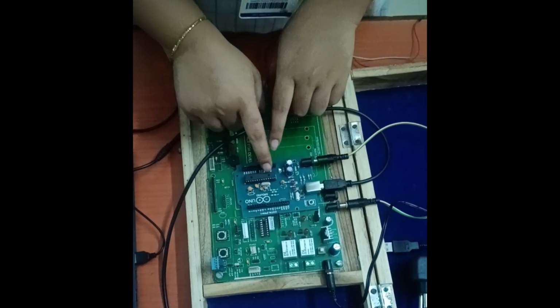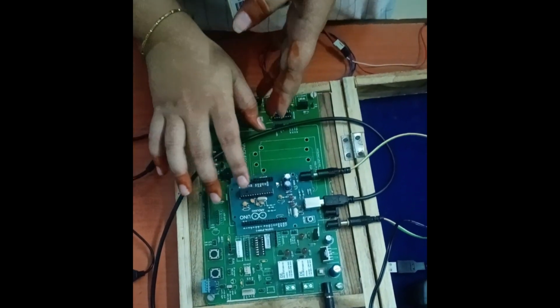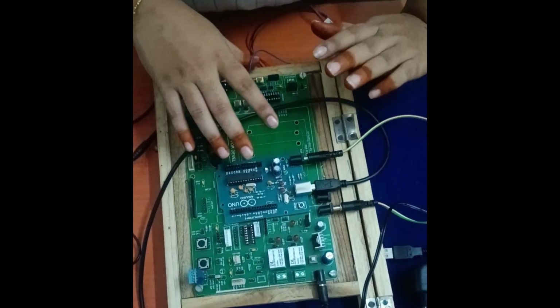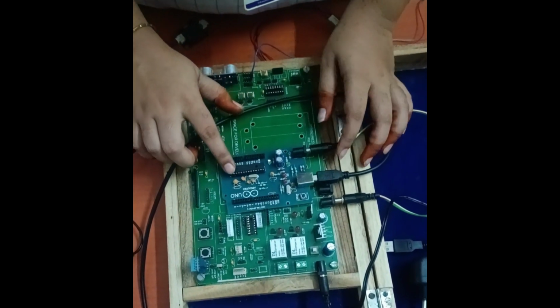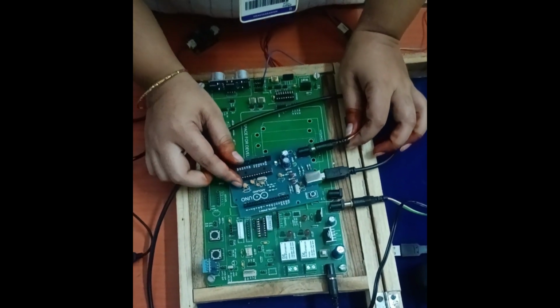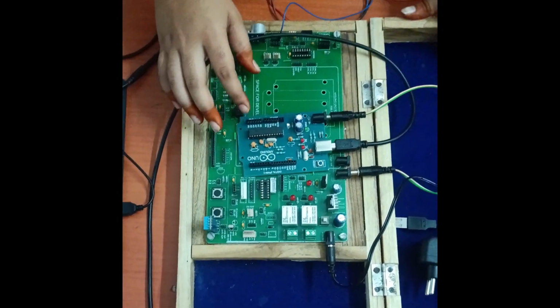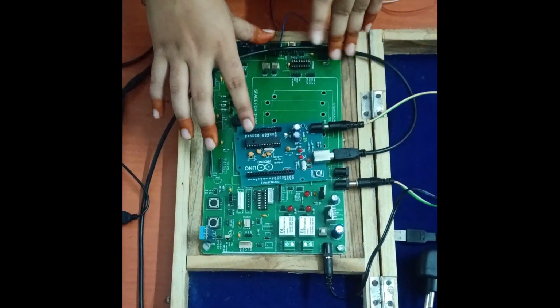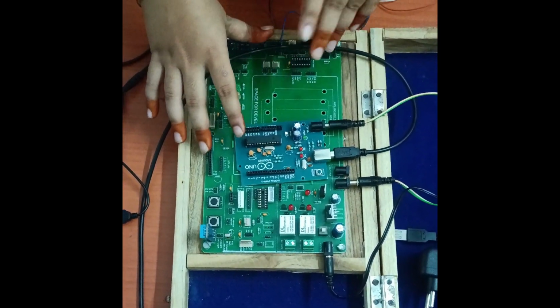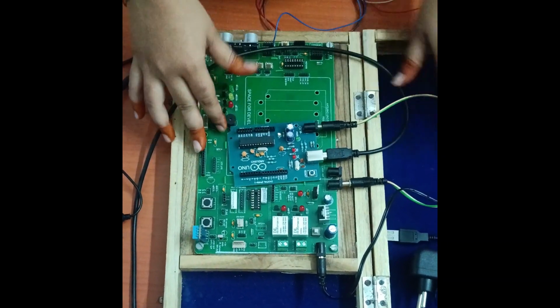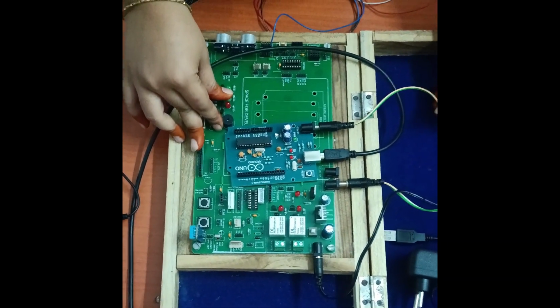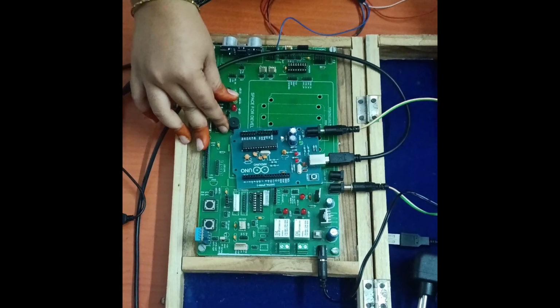The ATmega328P has processor and memory, AVR CPU at up to 16 MHz, and we have security and peripherals. The ATmega16U2 processor has an 8-bit RISC-based microcontroller, and we have memory: 16 KB ISP flash, 512B EEPROM, 512B SRAM.